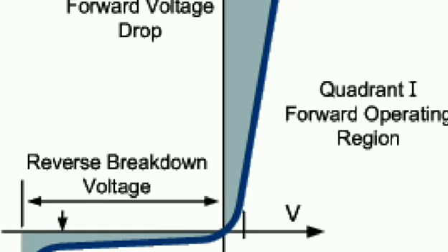What can we call that voltage? Cut-in voltage, and a third word, we can say knee voltage. You can see here I have given the name V suffix K double E. This is nothing but the knee voltage. So if there is an exam question on cut-in voltage for silicon, knee voltage for silicon, or barrier potential, all have the same meaning.